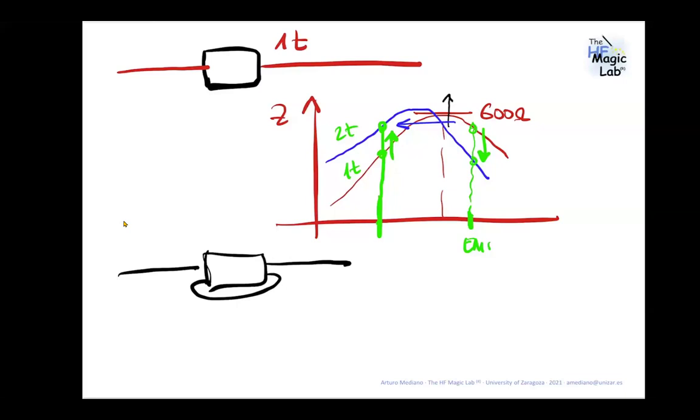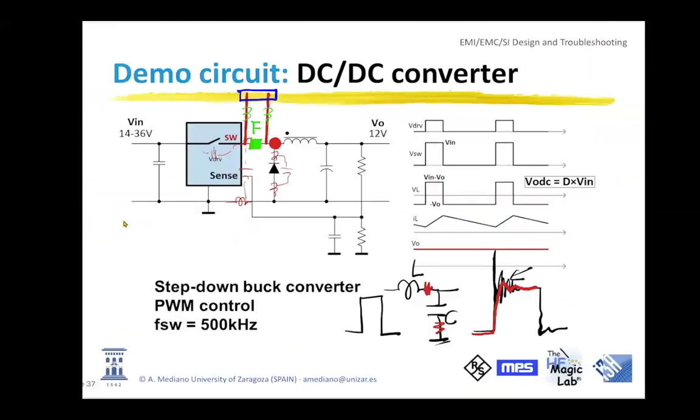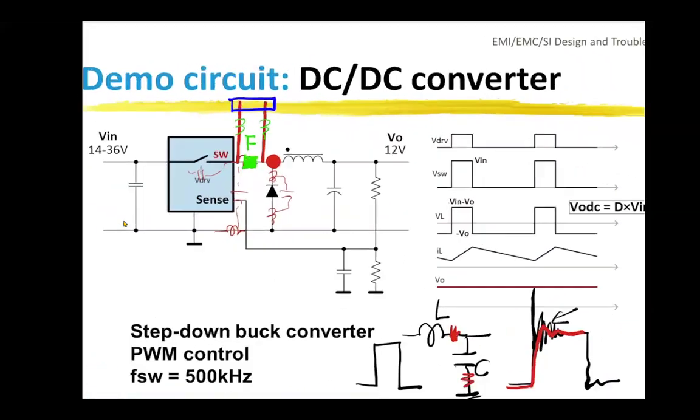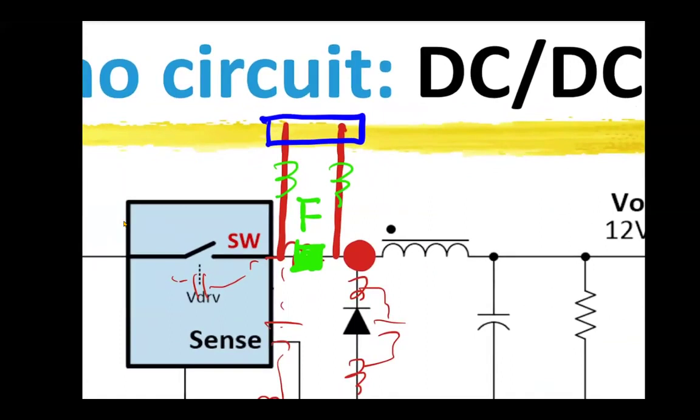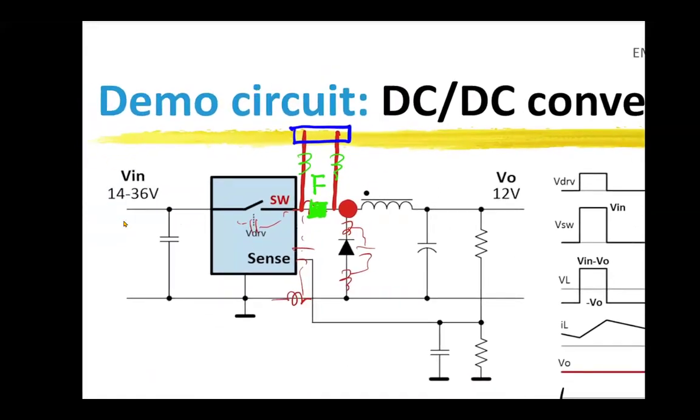Great, thank you. Next one is, where was the tuning jumper located? In parallel with the power supply to the big decoupling cap? No, it was here. This is what I explained. Probably the question was sent before I was explaining. The jumper is here, short circuiting a ferrite that is at the output of the DC-DC converter to demonstrate that the ferrite can kill a resonance.